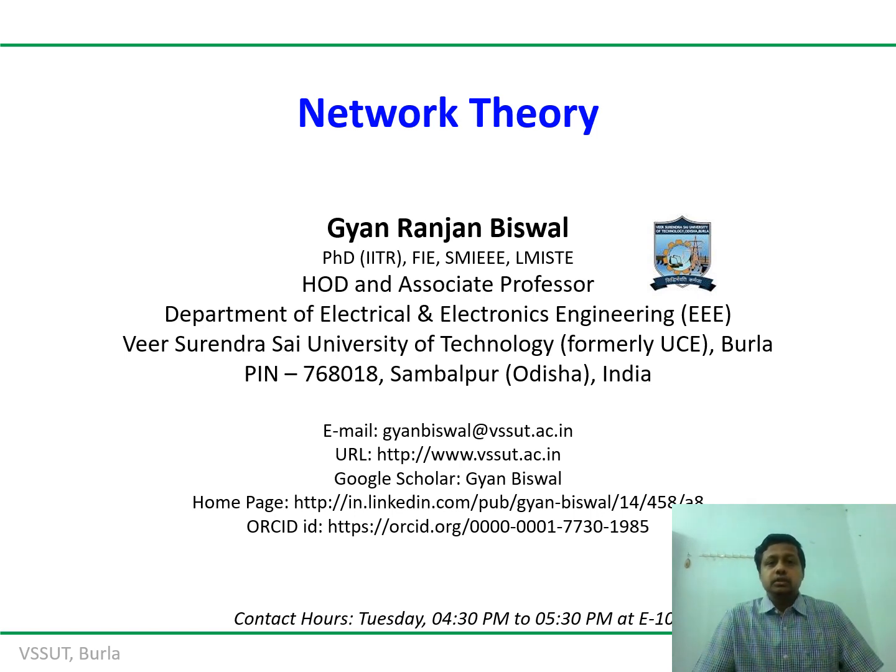Now the question comes: why not six phase or nine phase? Isn't it possible to have a higher phase supply? Certainly yes, the answer is yes. But again the number of conducting paths will increase equally, and it will add additional burden in terms of operation cost and, most importantly, maintenance cost as well. At the end of the day, it doesn't matter what technology you enjoy, as an end user you ultimately have to bear the entire cost. Your utility or the power generation company is not going to bear that cost; they are going to transfer it to you.